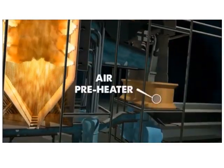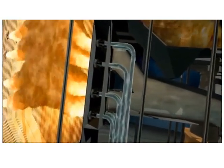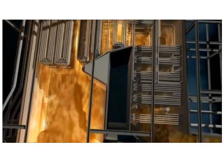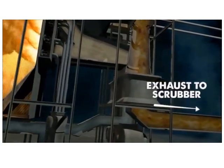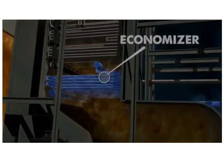For boiler operations and control systems, variations in the boiler outlet steam pressure are often used as an index of an imbalance between fuel energy input and energy withdrawal in the output steam. A great variety of combustion control systems have been developed over the years to fit the needs of a particular application. Load demands, operating philosophy, plant layout, and types of firing must be considered.